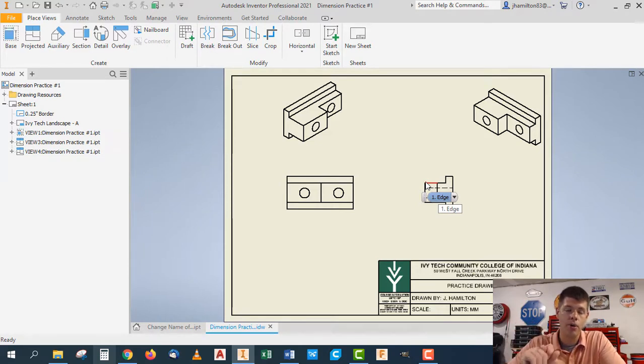Save all your part files and drawing files and assembly files for a project inside of a folder together. They all need to stay together. Give them names that make sense at the beginning that you like, and please don't move them in the middle of a project. You will run up against all kinds of file referencing issues and file location issues that will drive you insane. So take that as some sage advice from me. I've seen it happen to enough people early on. I'm going to help you try and avoid it.